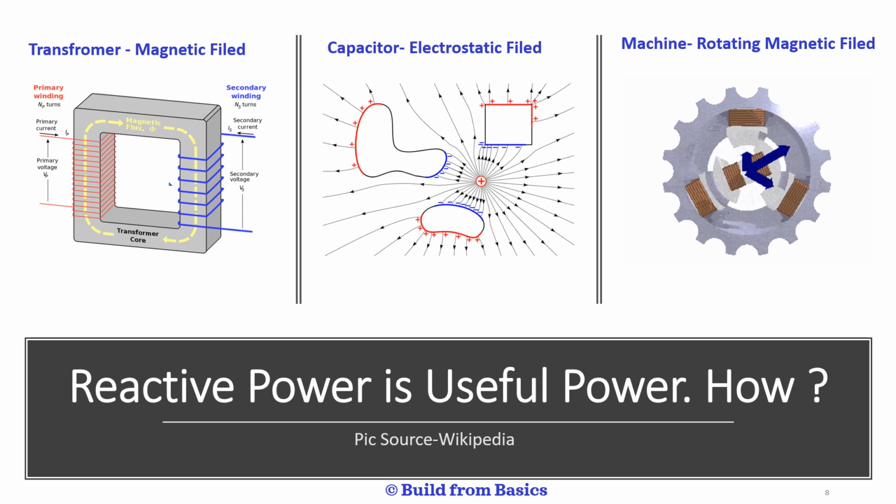So we use one reactive power against another, because to compensate the lagging reactive power consumed by the inductive nature of the load, we use capacitors, because capacitors basically produce reactive power. By controlling this reactive power, we can also control the voltage in the power system.